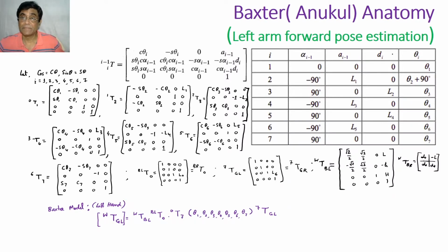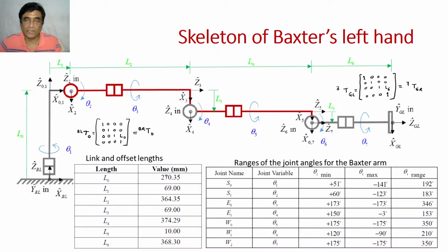The moment you have DH parameters, so these are links, this is the twist angle, all sort of things you must recapitulate, and this is your common normal, and this is the distance between common normals, which you can write in millimeter or centimeter. But the thing is, for running numerical methods, you should have some scaling. It will be good if all these are described in terms of meter. So the DH parameters, L1, L3, will be smaller, so it should not deal with such big numbers in numerical methods. So you can just scale them in meter.